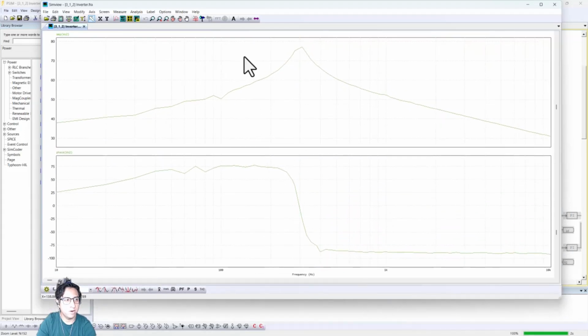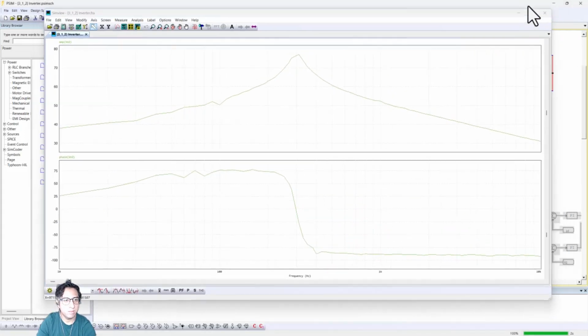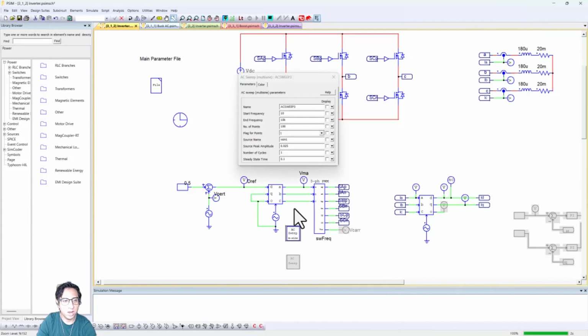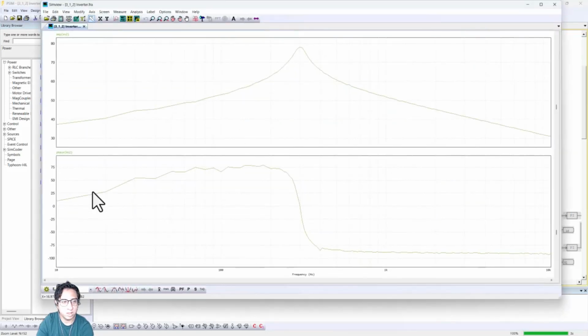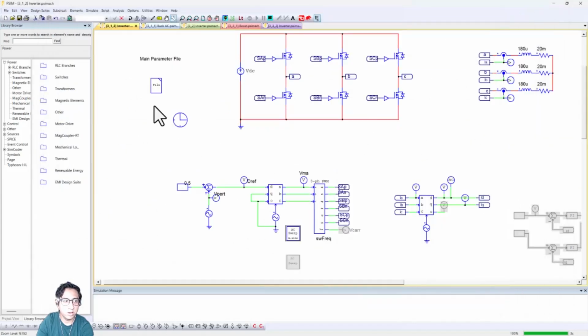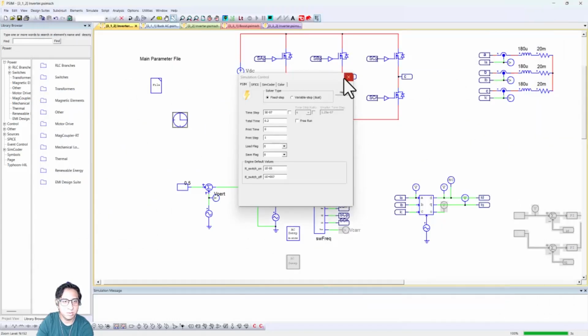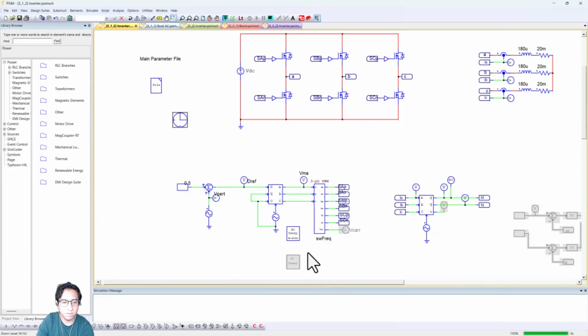So this looks far better than what we had previously, and we can actually keep improving on it. We can place maybe more points. Maybe we need a bit more amplitude, so let's go with double what we had previously. You can see it's still fairly quick. We have a bit more definition, something a bit smoother here. Another thing to look at always is time step, having enough time step for the actual waveforms we want to look at.